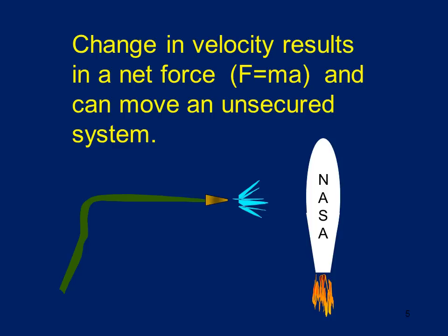And so NASA will use nozzles on the rockets. Now those are supersonic generally, and so it's interesting that those nozzles are reversed, they're actually a diverging nozzle. The area is getting larger even though the velocity is going up, and that's what happens when you get beyond sonic velocity.